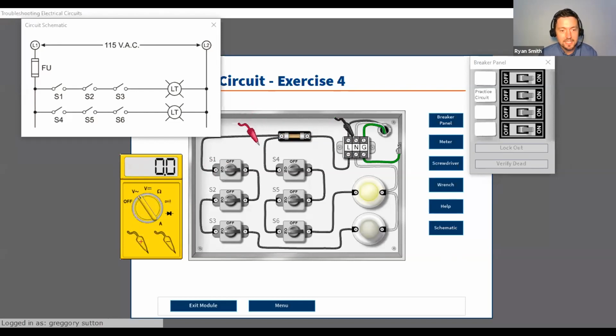I guess I got to go to this S1 over here because that's on the way to the bad light. Go here, 114. Go to the next one on the other side, and I'm gonna see 114. Okay, that's good. I still got power. Here. Okay, still got power. I'm gonna go to here. I'm happy continuing going the systematic way you taught me earlier in the class.